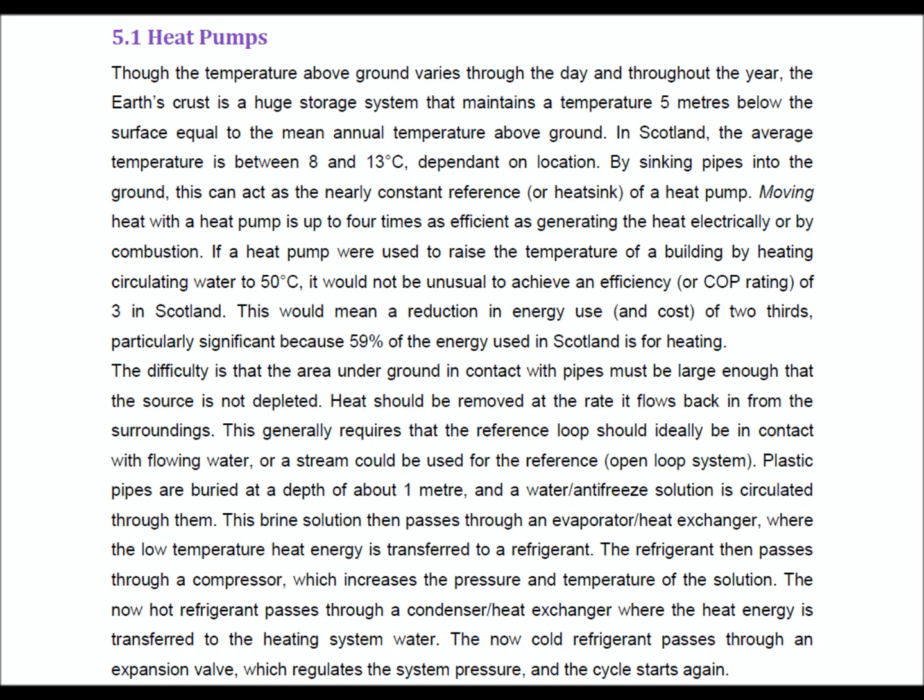It transfers that energy into the heat pump, where it's upgraded by means of a compression process, and that upgraded energy is then passed usually into either water or air used to heat a building space.